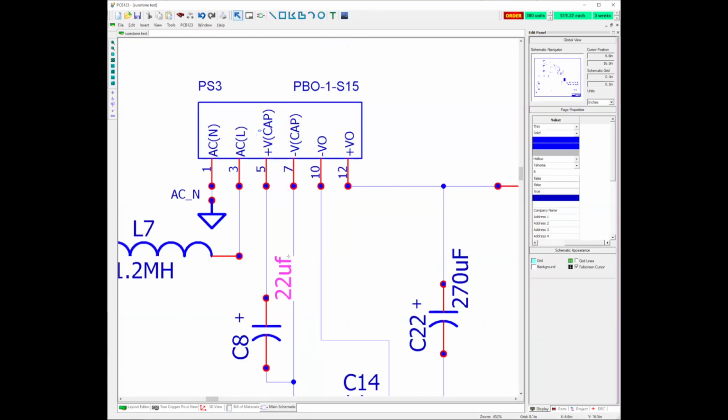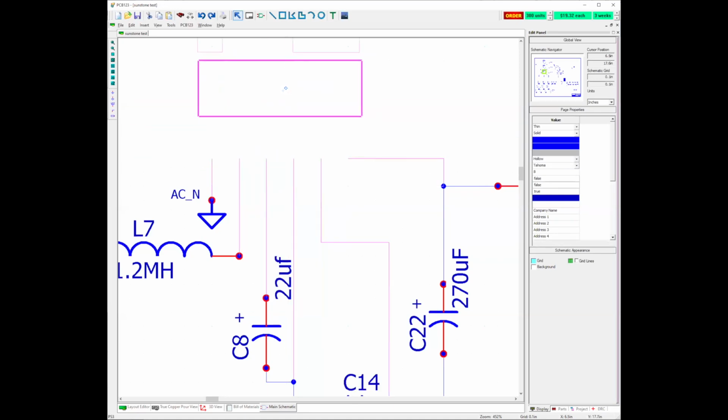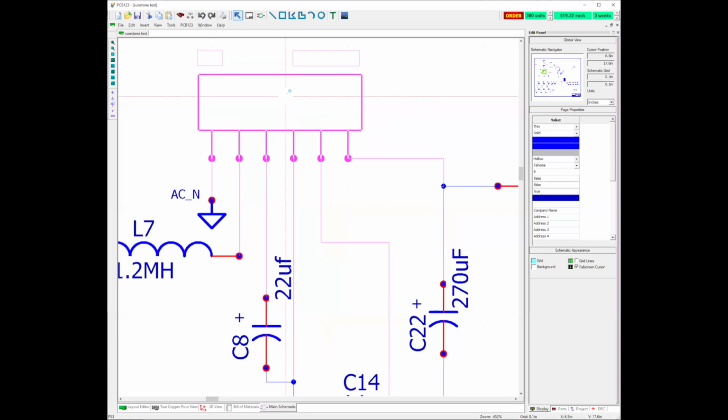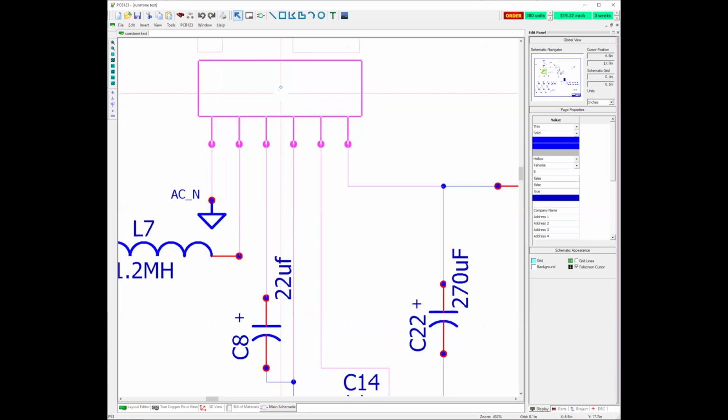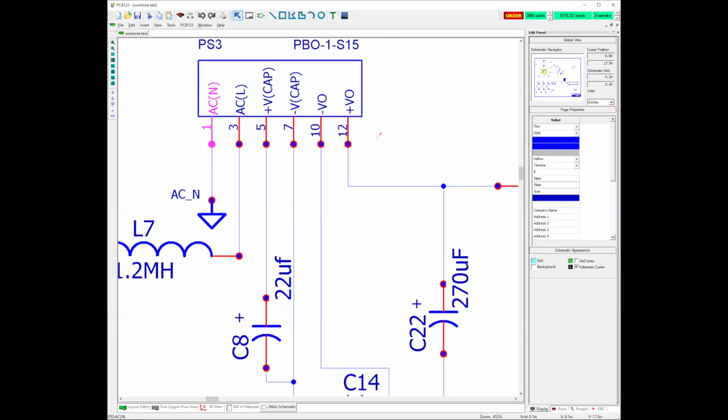So when you're moving a part that has more than a couple of pins, be real careful that if you move it sideways across the pins, versus just stretching wires, you don't end up with a wire from pin to pin. Anytime you see that on your schematic, it's probably a mistake. You probably didn't do that on purpose, and it's going to be very difficult to fix.